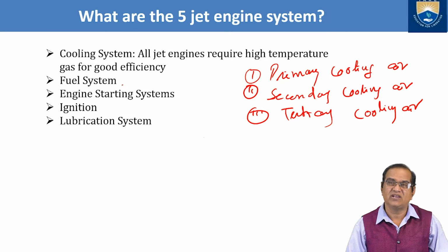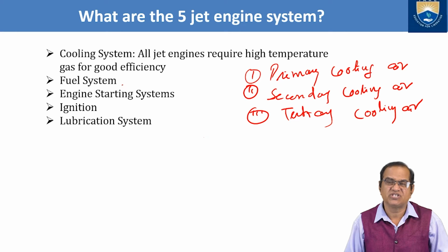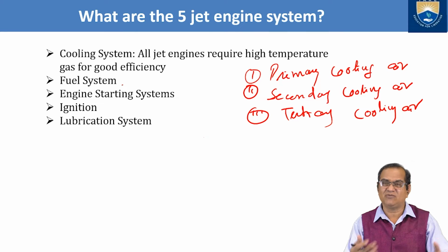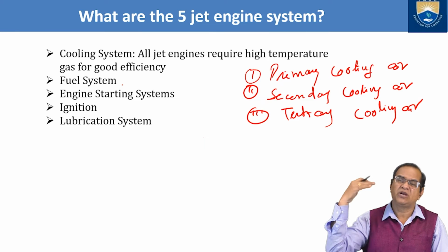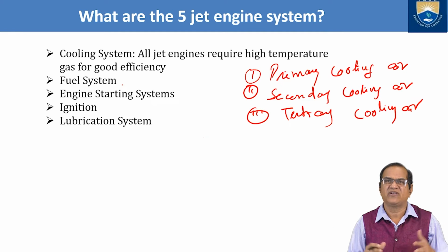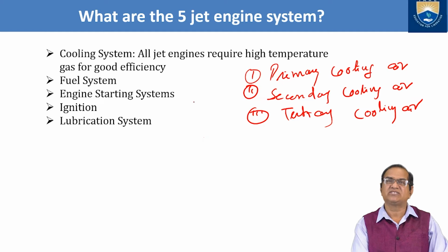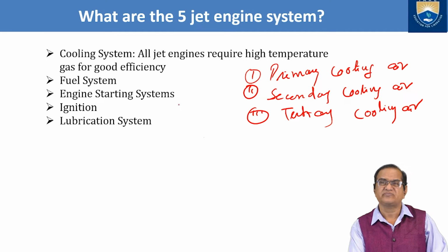Another one: in most of the aircraft we have the pressure pump system, in which a pump is fixed, and that will suck and give a pressure. With the pressure, fuel will be supplied to the engine. In this type of aircraft, anywhere you can put the fuel tanks, below, above, or any place, and your fuel supply will be there.